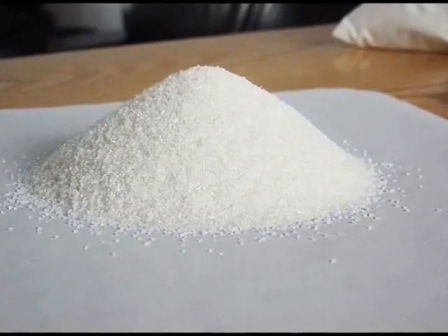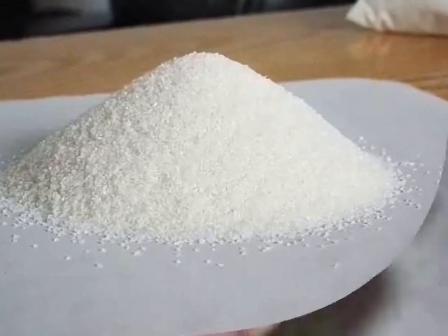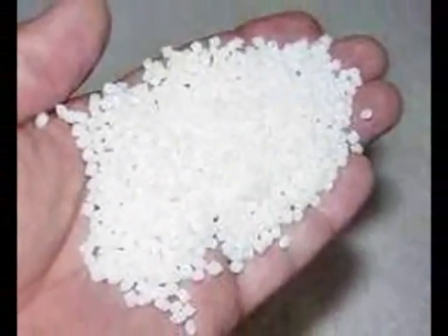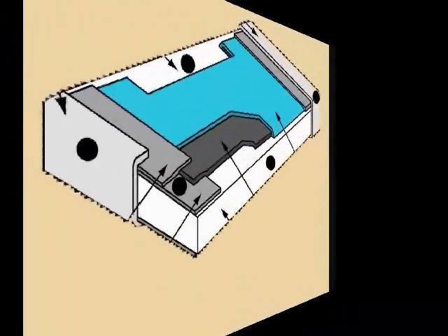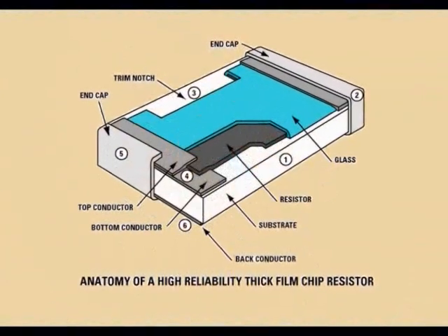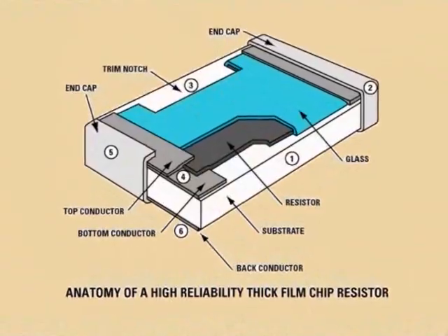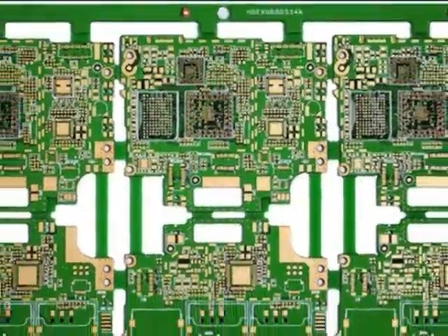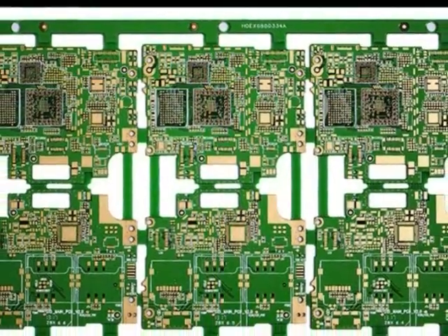Thick film resistors are made by placing a very thick conductive paste of ceramic and metal on a substrate of ceramic and aluminum oxide. This type of resistance is called cermet. Cermet resistors have the same characteristics as metal film resistors. In general, these types of resistors are used in the construction of chip resistors and multi-resistor networks implemented on the printed circuit board, PCB, and high-frequency resistors.